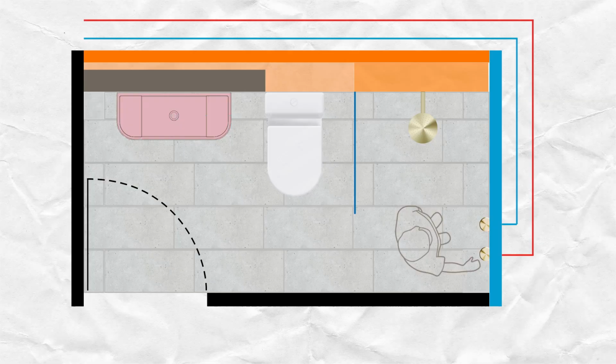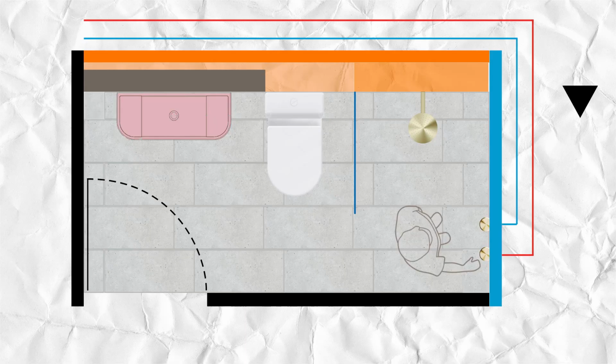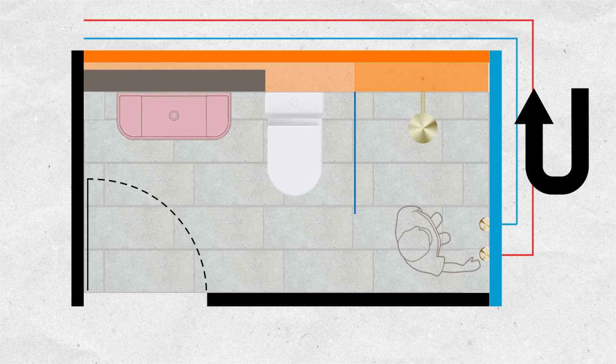Another important detail is the location of the shower taps. I've placed the taps at the entrance to the shower recess as opposed to underneath the shower head, so the occupant doesn't get splashed with cold water when first entering the shower. This will attract a little more meterage of pipe when roughing in, but worth the investment for the quality gained.